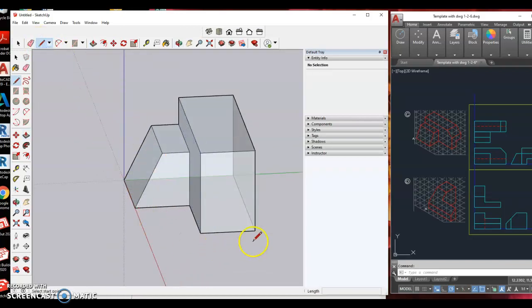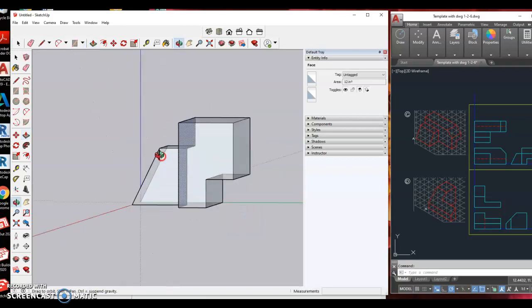And we'll do the same thing on this side. We'll get the pencil, and we see that we have a channel over here. The channel starts, I'm just using that bottom corner as a reference. It's going up on the edge, and that creates a point. And now I can come out along the axis, parallel to the axis 1, and I'm on the face going down 1. Then we switch over to our push-pull, push it all the way through, and now we have that.